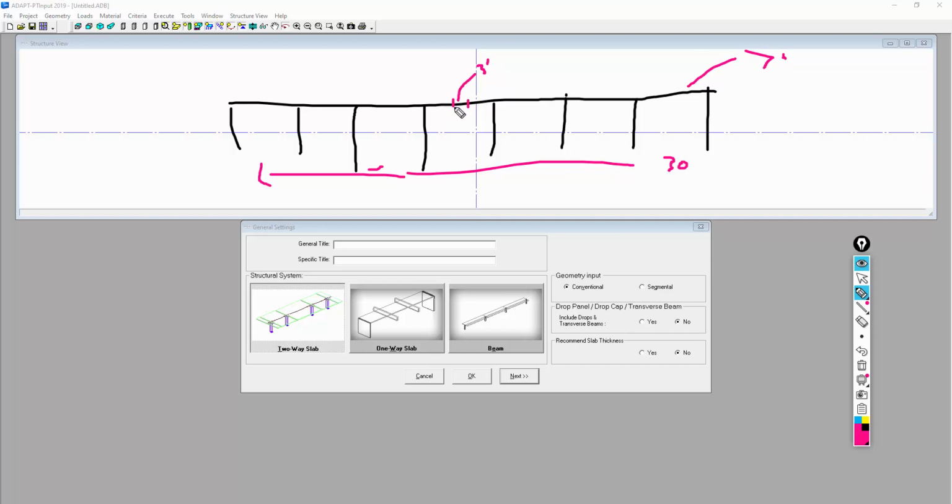That may not be the actual place that it's positioned. It might be shifted towards a column or maybe a moment inflection point, but for this example we're going to put it right in the center of span. And another assumption we're going to make is that this pour strip is shored until it's poured back. So after we stress both sides, and we're going to use blue here, we're going to say there's a tendon anchored here at the face of that pour strip. It's stressed, and then on this side this tendon is stressed.